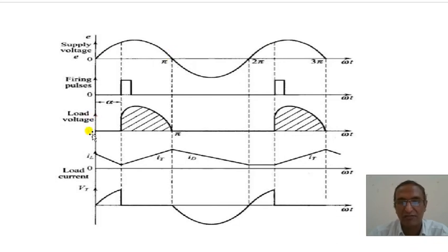You can see here the thyristor is forward biased, but there is no voltage flowing through our thyristor. You can see here our voltage is 0. So when I apply a short trigger pulse at an angle of alpha, the thyristor starts to conduct at the point when the input voltage is applied. You can see here, whatever the input is applied, the same voltage is supplied to the load resistance. This is what happens during the positive half cycle of the input.